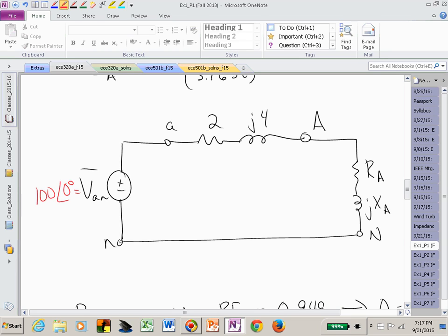Because in this problem, all I'm asking for really is this phasor voltage and the impedances, and it really doesn't matter because I could draw 0 here or I could draw 0 somewhere else relative to this sinusoidal steady state. What's important is you know the magnitude of this generator voltage and the impedances.